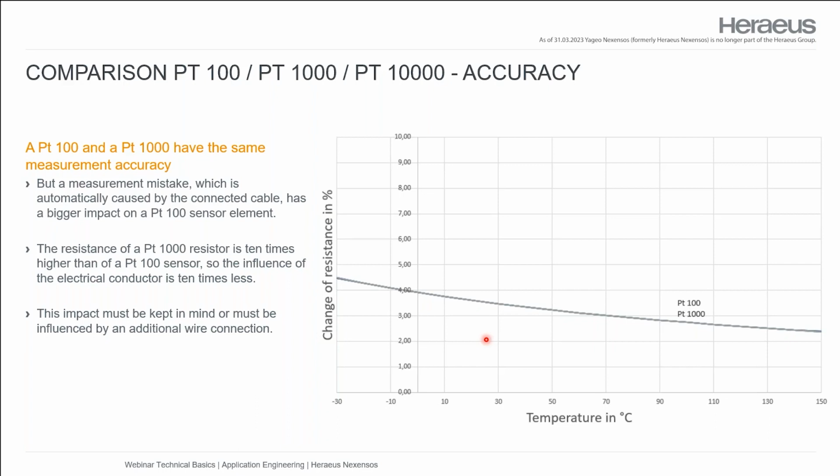No, the response time has more to do with how you protect your element. Typically, you don't use it without any protection. And the second point is how you contact the element, the sensor, to your measurement probe. And this is not so easy to say. You have to adjust your packaging, that means your housing, to your applications.